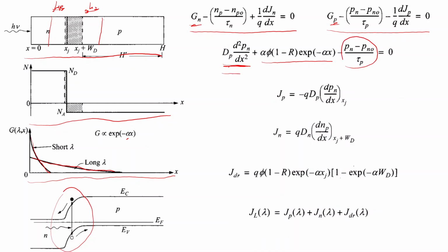So that is this continuity equation for holes in the n-type region of the semiconductor. Here, from this region, how much we will contribute because of diffusion. The solution of this differential equation, this continuity equation, will give us Pn as a function of x, the distribution profile of minority non-equilibrium charge carriers, which we discussed qualitatively previously.